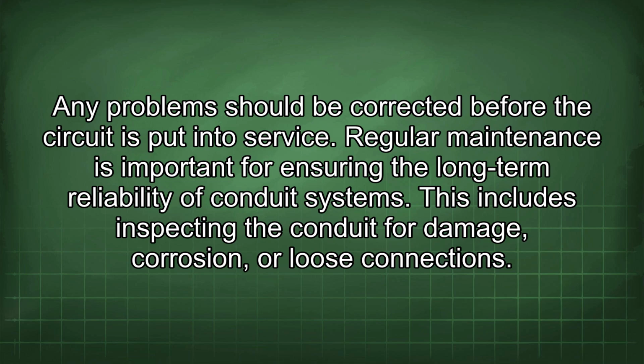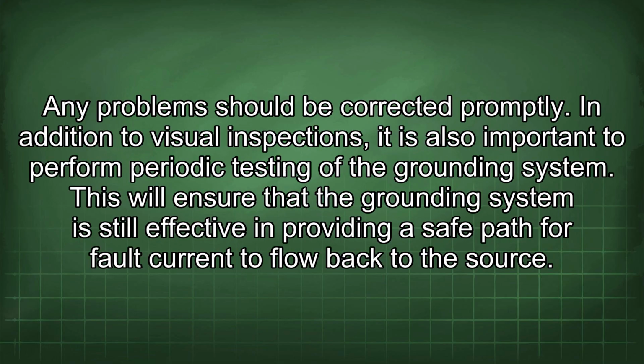Regular maintenance is important for ensuring the long-term reliability of conduit systems. This includes inspecting the conduit for damage, corrosion, or loose connections. Any problems should be corrected promptly. In addition to visual inspections, it is also important to perform periodic testing of the grounding system.